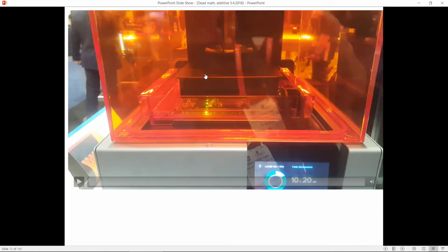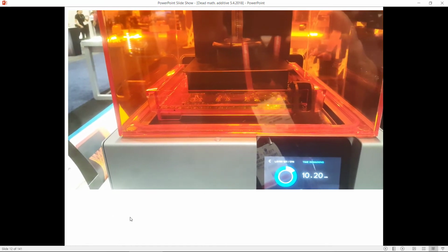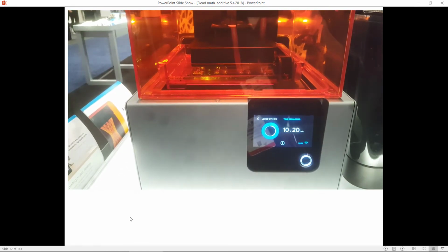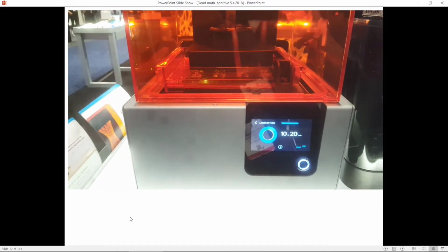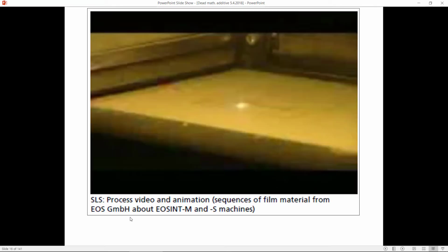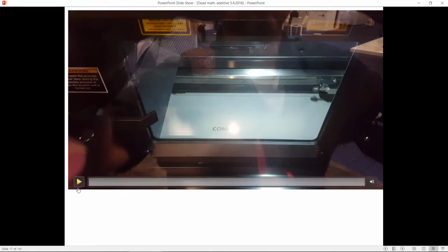So, look at a laser machine, and this is with a resin. Essentially, it's curing the resin, right, as it moves along. Then there's multi-laser systems. Here's another sintering machine where this is a powder, and it's going to make some kind of solid. So this could be a steel powder, it could be a titanium powder, it could be an aluminum powder.